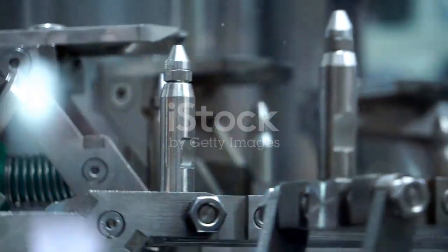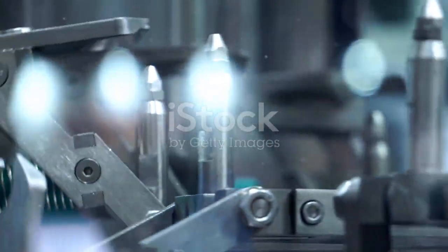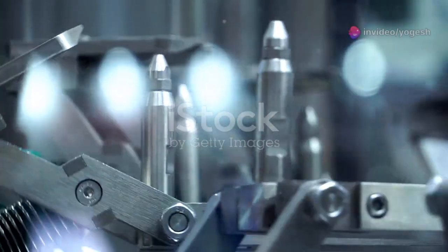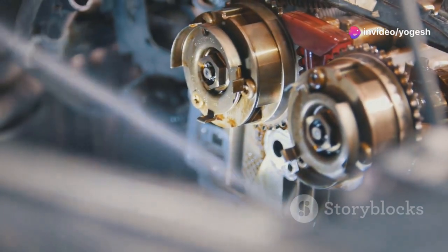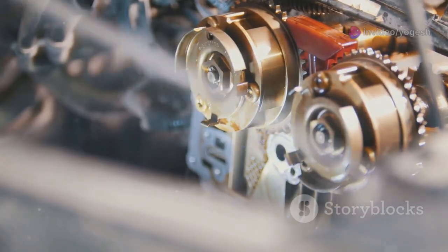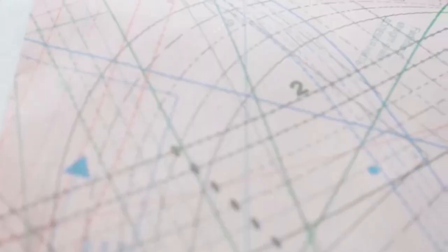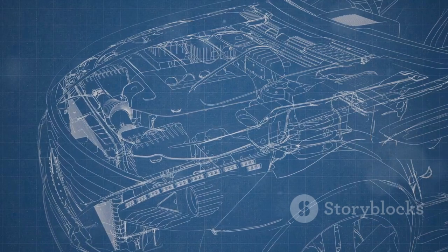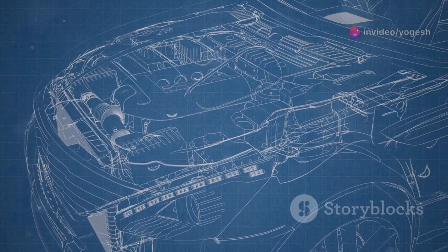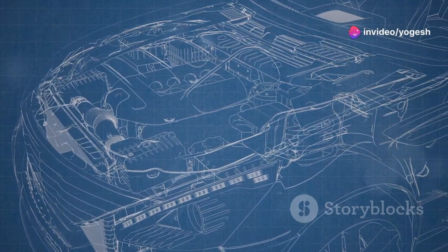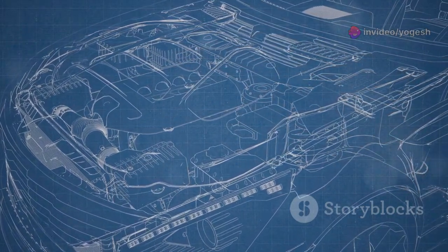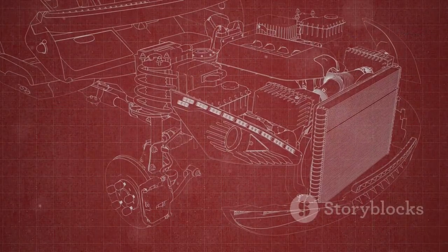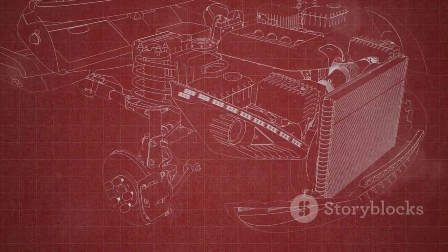Visual tools like exploded and sectional views are essential for understanding assemblies. Exploded views show parts separated along an axis, clarifying how they fit together and in what order. Center lines guide the eye and show alignment. Sectional views cut through the assembly to reveal internal details, crucial for showing how seals, bearings, or gears are positioned. These views often highlight critical steps in the sequence.